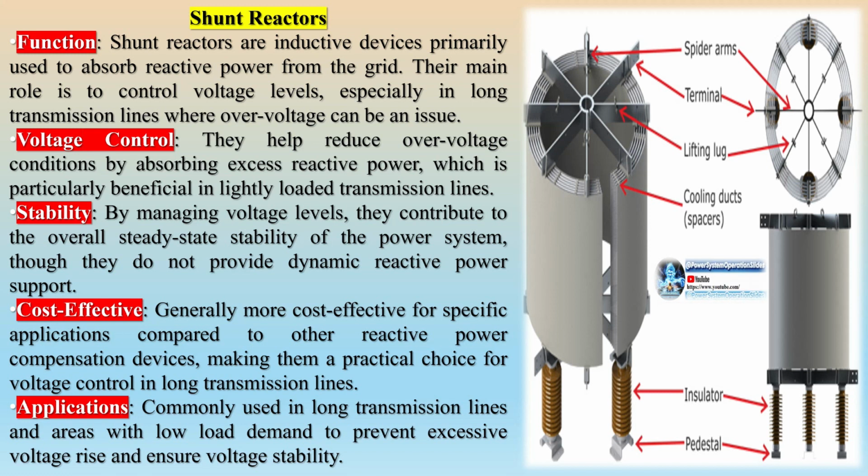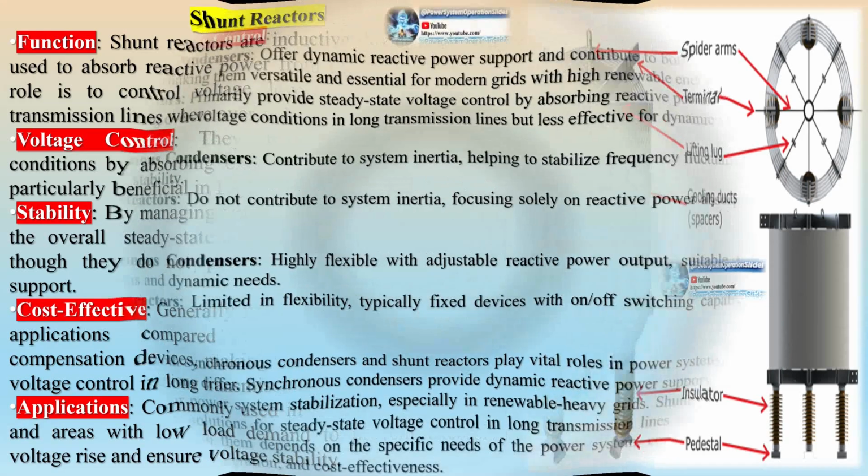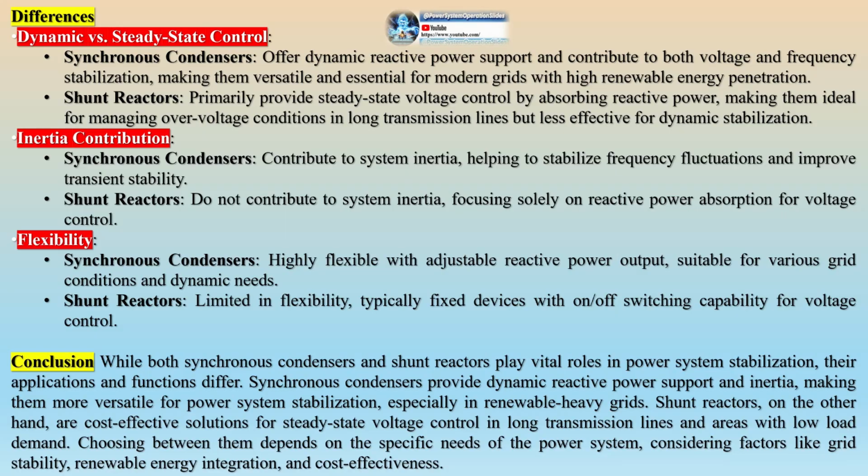Synchronous condensers are particularly useful in grids with a high penetration of renewable energy sources. They are installed at strategic locations within the grid to provide localized reactive power support, enhance voltage stability, and improve overall grid resilience. Unlike static devices, synchronous condensers provide both reactive power and inertia.